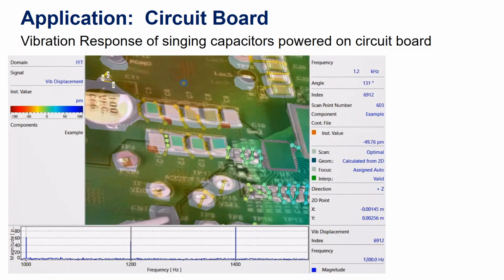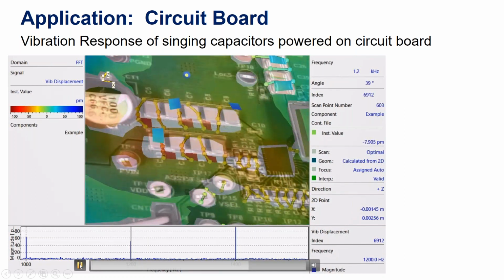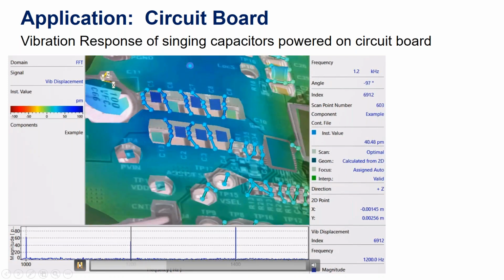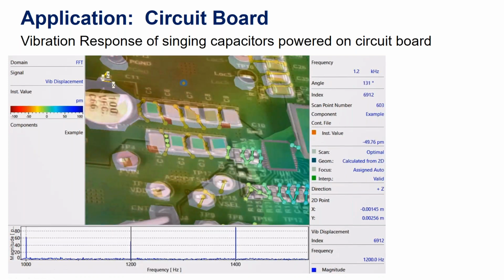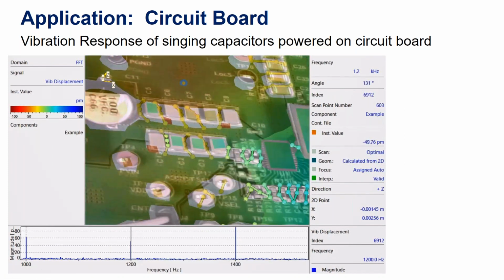What we mean by that is, as we're powering up this board, this is a power amplifier board, the current going through these capacitors, the little elements that you see vibrating back and forth, that's enough to cause a sound output. Even though each one of those might be vibrating, you might not be able to hear the individual capacitors. At some level, having a series of these, the vibration gets amplified and it does become audible.